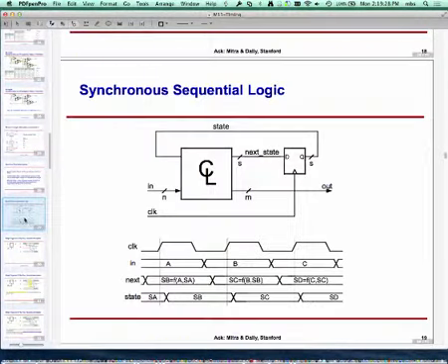Okay, so now why do we care about it? Delay through the combinational logic in itself is not of interest. What we really care about is, when we are designing sequential logic, the question which comes up is: will it operate correctly? How fast can I run my clock?